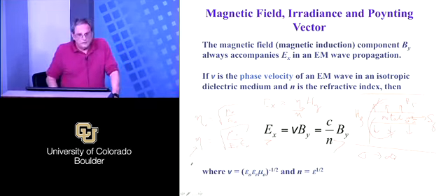This is one of the reasons why we need transmission lines. If we're at very low frequencies, for example, we have a circuit, and we look at the wavelength of the electrical disturbance. If we're operating at a megahertz, that corresponds to like 300 meters. And you don't have many circuits that are as big as 300 meters. So the wavelength's very big, so everything's equipotential inside of the circuit. There's no wave concept or anything. Everything's always at the same potential on the inside of there.